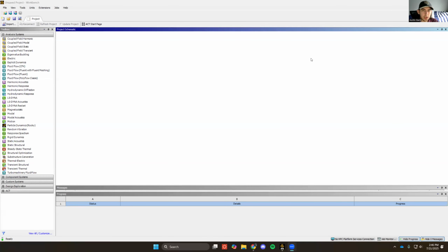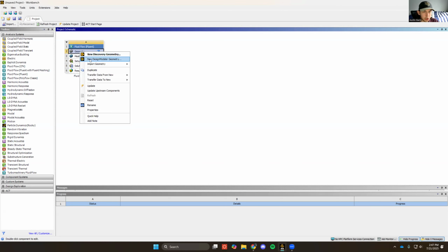I'm going to be showing you guys how to do part two of Dr. Osbay's ANSYS Fluent project. So to start, I'm going to be selecting Fluid Flow Fluent and drag it over. I'm going to create a standalone system. Right click on Geometry and click New Design Model or Geometry. Double click that, let it open.